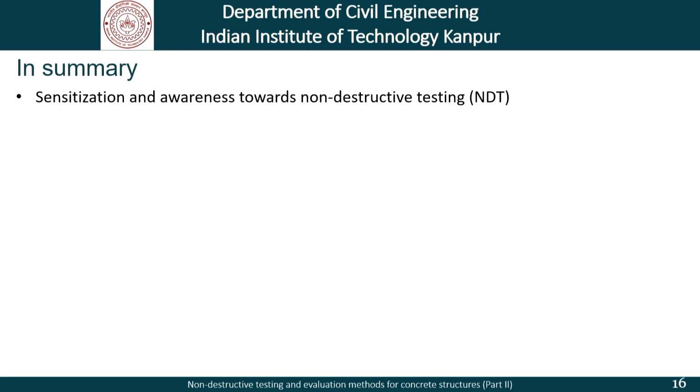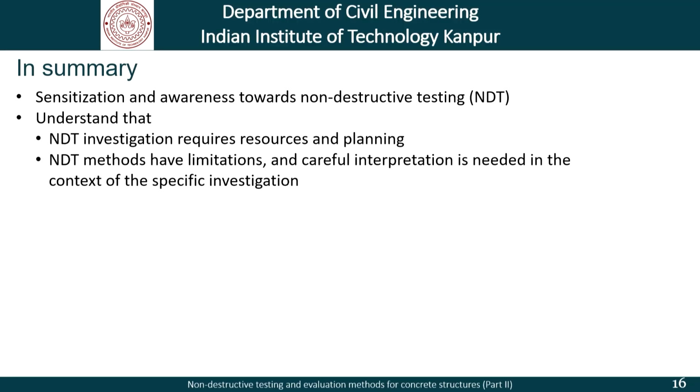So in summary, as far as our discussion today and the previous discussion, when we talked about the other non-destructive methods such as the Schmidt-Hammer, is concerned, it was more directed to create a sensitivity and awareness towards non-destructive testing, to understand that NDT investigation requires resources and planning, and the methods have their own limitations. We have to be very careful in making interpretations, and that has to be carried out in the context of the specific investigation being done.